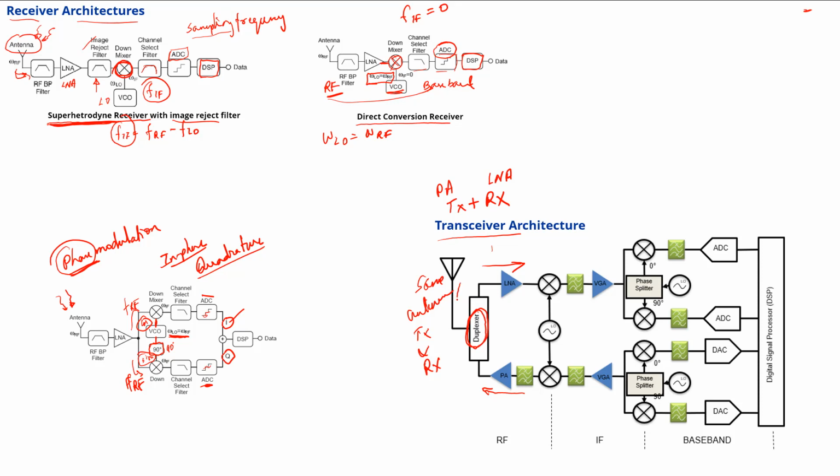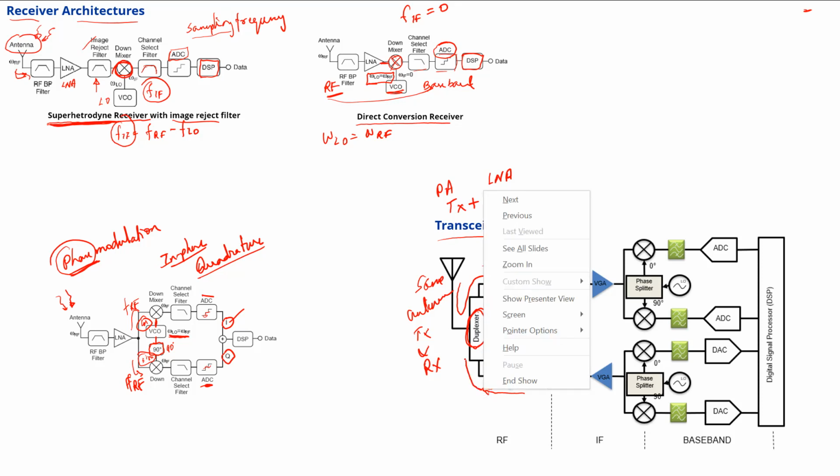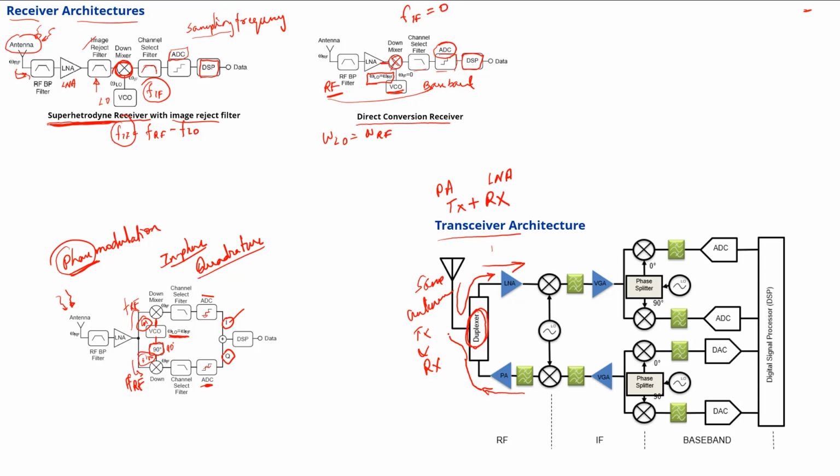In other words, whatever the antenna receives goes to the receive chain, and whatever the duplexer is fed as the input RF signal is going to go into the antenna. So the rest of the architecture for the receive chain is no different than, for example, the digital IF receiver that we have seen, with both the in-phase and the quadrature phase components.